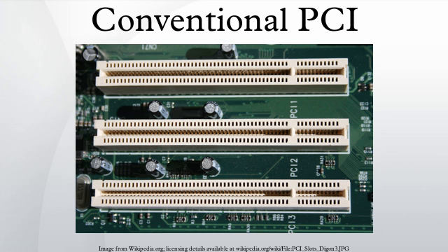PC/104-Plus and PCI-104: the PC/104-Plus and PCI-104 embedded form factors include a stacking 120-pin PCI connector. Other physical variations: typically consumer systems specify N PCI slots without specifying actual dimensions of the space available. In some small form factor systems, this may not be sufficient to allow even half-length PCI cards to fit. Despite this limitation, these systems are still useful because many modern PCI cards are considerably smaller than half-length.